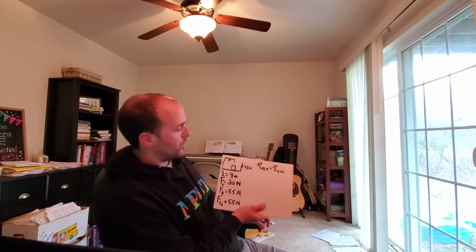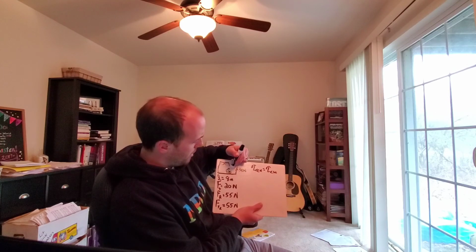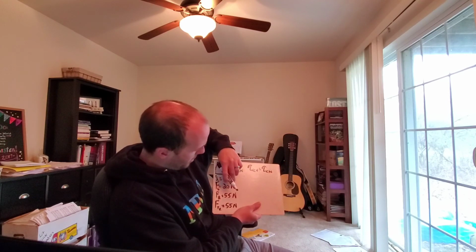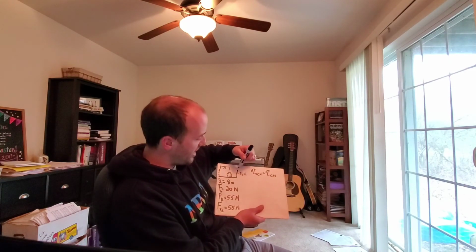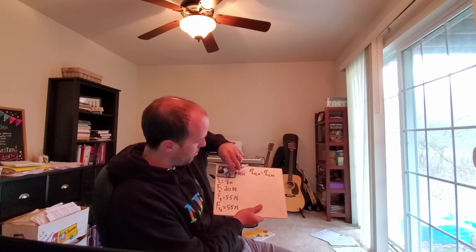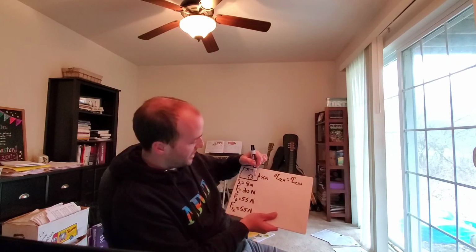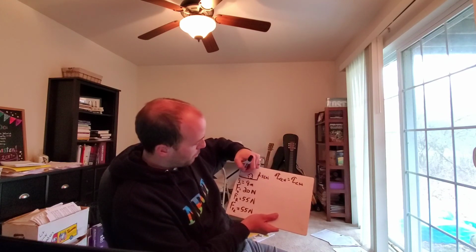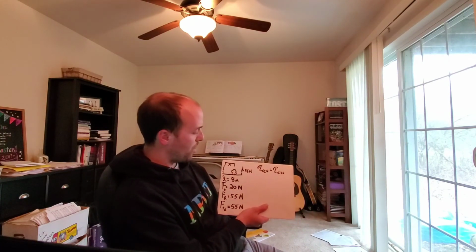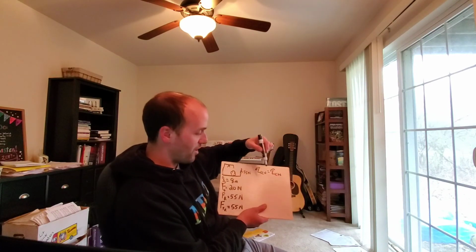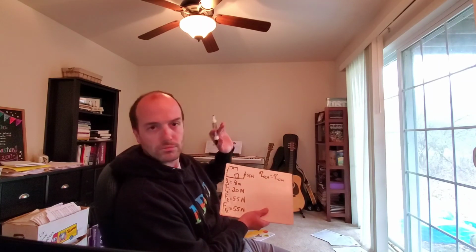What forces would cause this system to rotate counterclockwise? Well, the rock acts down. That would apply force that way. That's clockwise. The weight of the beam, same thing. This tension in the chain, the right side chain here, that's our counterclockwise torque. What's nice is this chain acts up, our moment arm is horizontal, that angle is 90 degrees, and sine of 90 degrees is 1. So I'm not going to write the sine theta for any of these because, again, the rock is down, horizontal. The beam's down, horizontal. We're good.